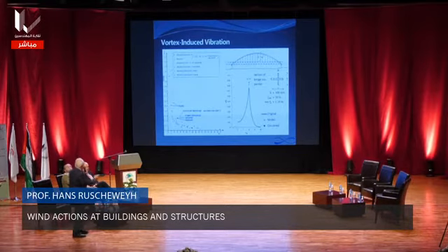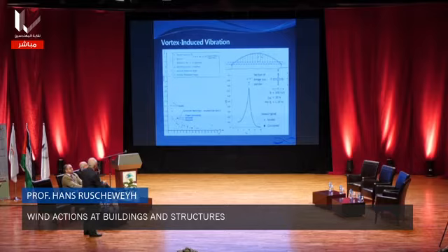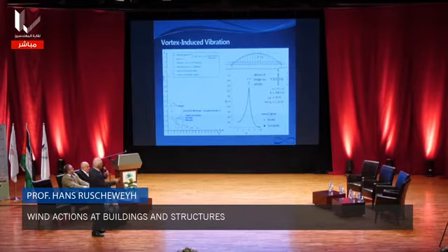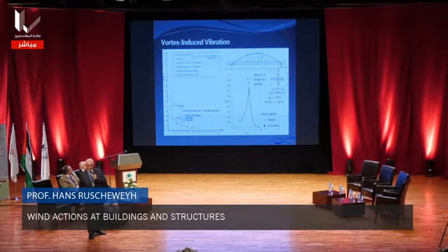so the black dots and the crosses are very important. On the right side, you see investigations on a bridge hanger. The bridge hanger was not a cylinder, it was a cross. You see it on the right side there, 300 millimeter, and there is in the middle a black point. This is calculated by the method. The cross is a model test, and the curve is a full-scale measurement. So you see, the maximum values are very close together.